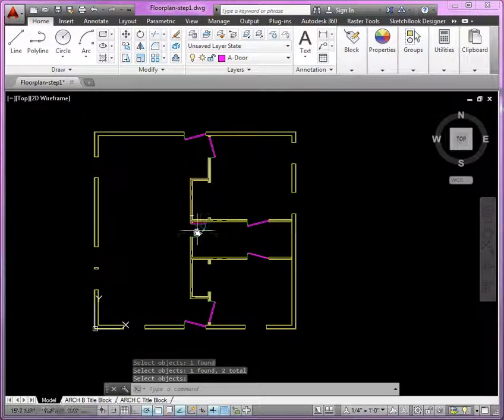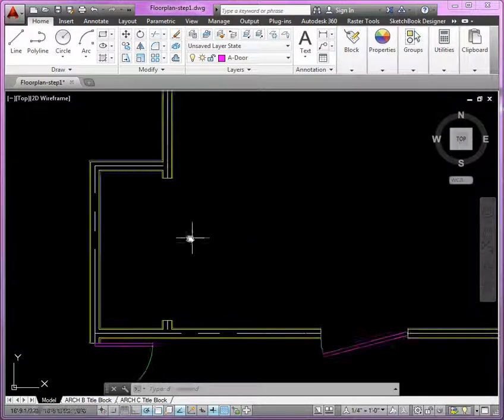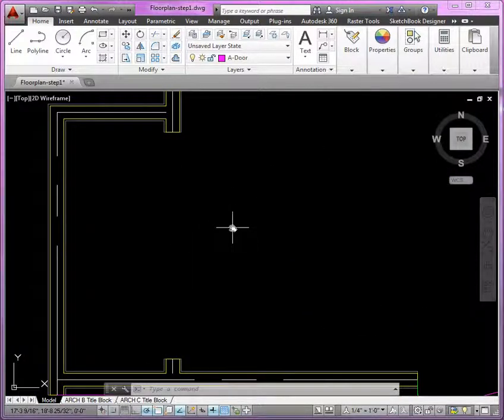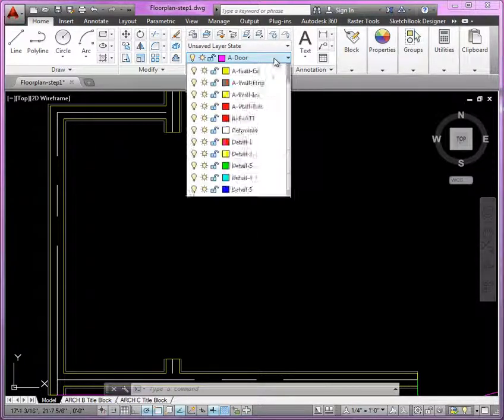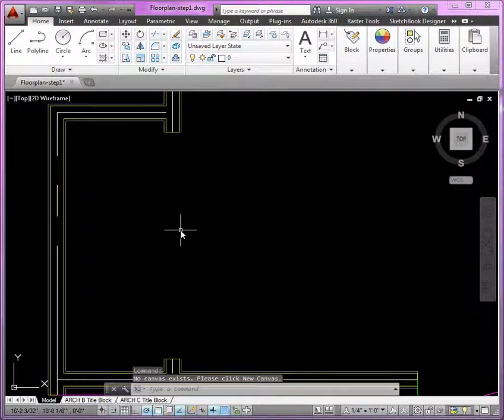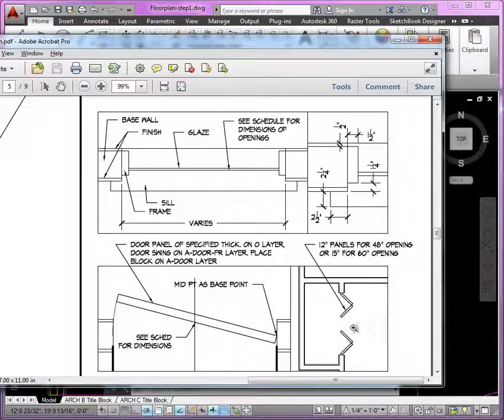Now, the last thing we have are the 2 bifolding doors, right? On the top, we've got a 5-foot, and on the bottom, we've got a 4-foot. So here's one way that we could approach it. If I switch to layer 0 here, all we're showing are the panels, right? And so with our 5-foot opening here, altogether 30 inches right here, but each of these panels is going to be shown as 15 inches, and then for the 4-foot, we're going to show 12 inches. And we could just lay them out 45 degrees or 30 degrees to one another, okay?